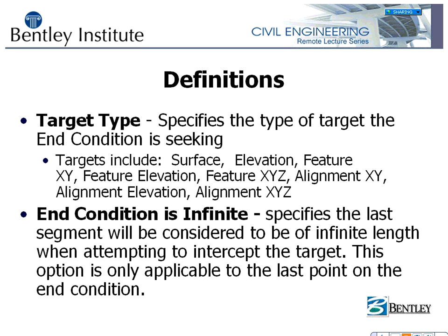One more thing I want to talk about is a feature that's been added. It's a little thing, but man, I really like it. It's in condition is infinite. In the past, if you've ever defined a decision table, you always want to make that last record about 5 million feet long or something like that to make sure it would tie in. Now we have this option to say in condition is infinite, and you can make it 3 feet long and just give it that option. It'll go forever until it knows it needs to tie in. It's a little bitty thing that they've added, but it's really nice. It's a handy tool for us to use, and we'll be utilizing that as the morning wears on also.